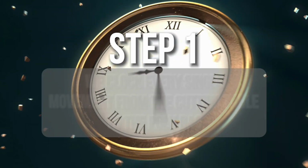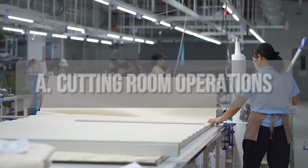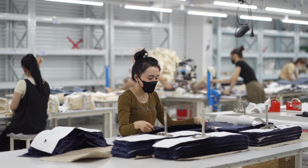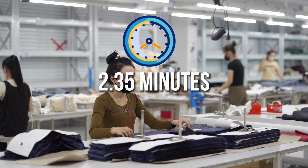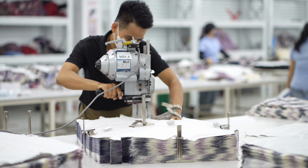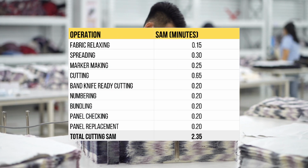Step 1. We clock every single movement from the cutting table to the polybag. A. Cutting room operations. First up, the cutting room. From laying out your fabric to bundling the final pieces, this entire stage clocks in at just 2.35 minutes. It's quick, it's mechanical, and it's where we set the pace for the rest of the line. This table shows the standard allowed minutes, SAM, for the cutting process.